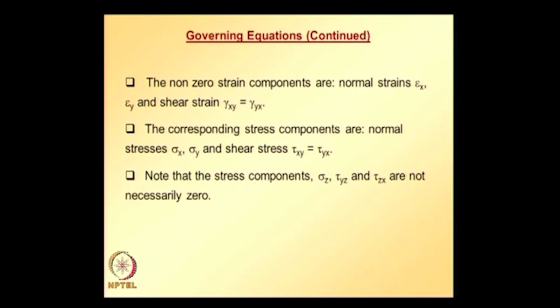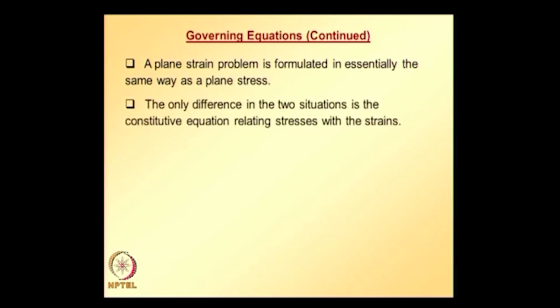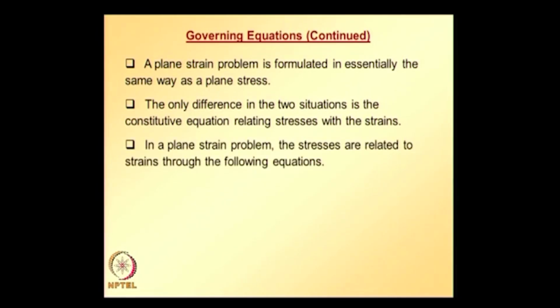And the plane strain problem is formulated essentially the same way as the plane stress problem that we just looked at. The only difference in the two situations is the constitutive equations relating stresses with strains, and in a plane strain problem stresses are related to strains through the following equation.